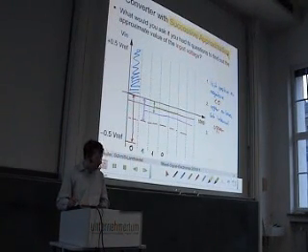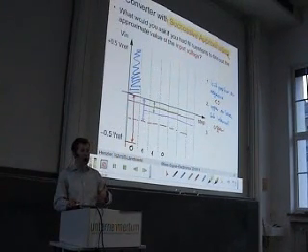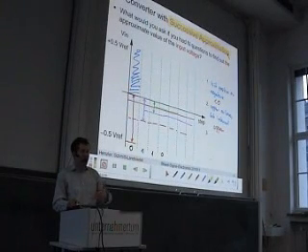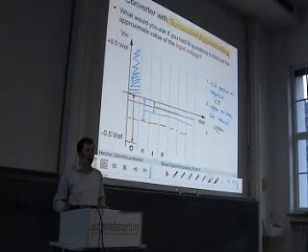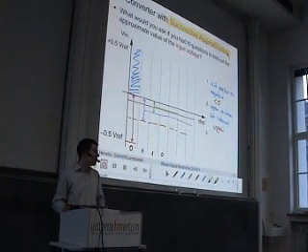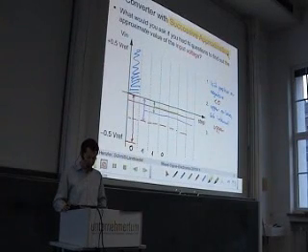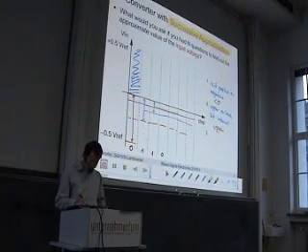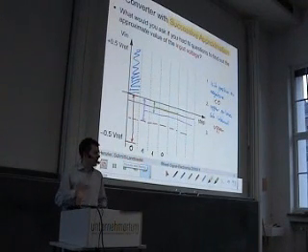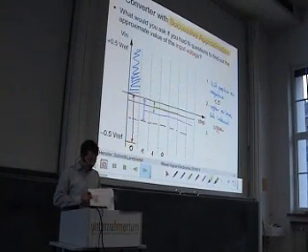It is called successive approximation because it performs this binary search technique and approaches the result step by step. So we do one step, then we have a very coarse quantization. After the first step, we know only the sign. After the second step, we know a little bit more than the sign, but we still have a very coarse representation of the input signal. And with each step, we gain one more bit and become more and more accurate.